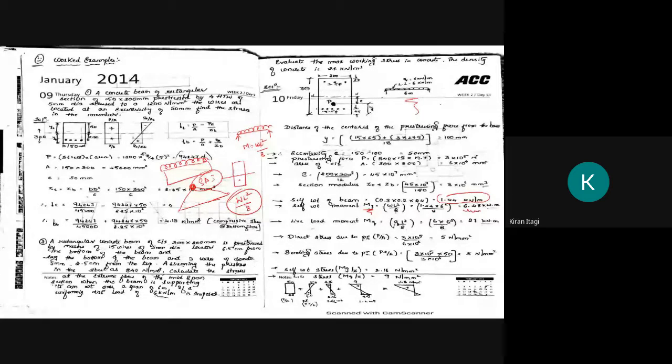So we have the moment with respect to dead load. First I will write down Wg, that is dead load. How much have I got? 1.44 kilonewton per meter. Then Mg, that is the moment with respect to gravity load, dead load. That is 6.48 kilonewton meter, correct?